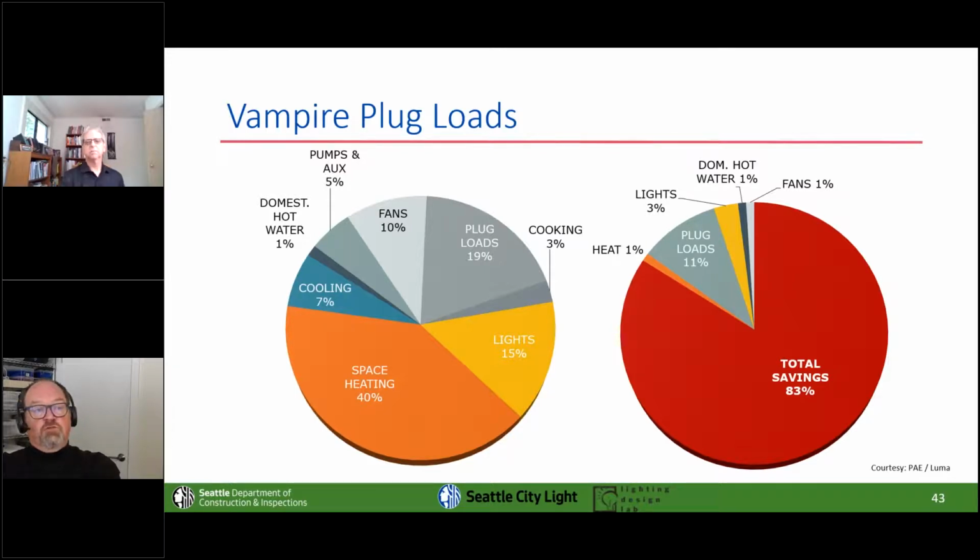And then again, of course, as Duane mentioned, one of the things that people usually complain about with these switchable outlets is, oh my God, I lost work on my CPU. They are labeled. They have to be labeled by code. Don't plug your CPU into one that's controlled, and you'll be fine. Won't be a problem. Okay, back to you, Duane.